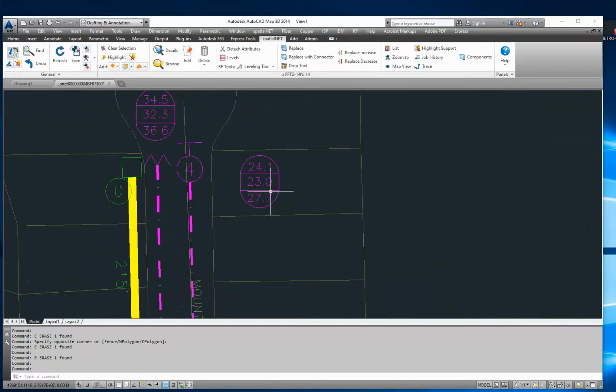Now up here, if you notice, it's a little bit hot and it has a tilt. So we have our 24 over 27. So there's about a 3.6 dB tilt, which means we're going to have at least a 4 dB equalizer or higher to fix that tilt. If we leave it a 4-port, but since it's so hot, I'm actually going to replace this.